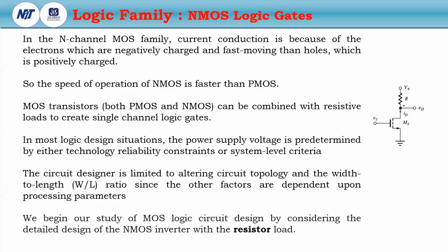So then we will use only NMOS or the PMOS or both the NMOS and PMOS in the logic circuit to make the larger circuits in a single chip. So what is the disadvantage of the resistance where we use? That is the high power dissipation, the heat generation, the nonlinearity effect, and the noise prone element. So for this reason, we are not using this resistance R.